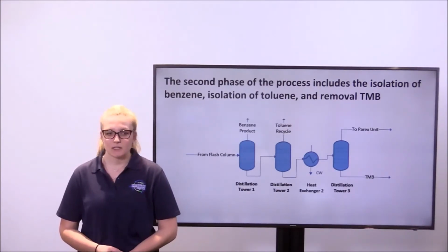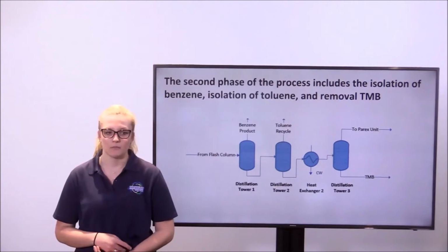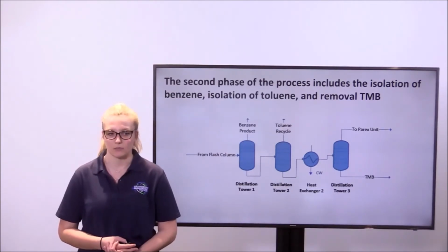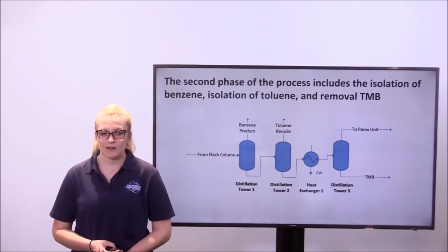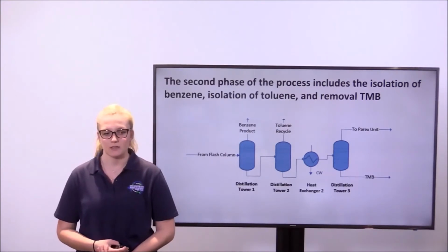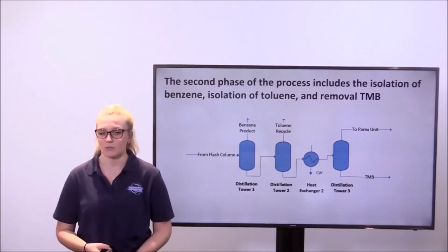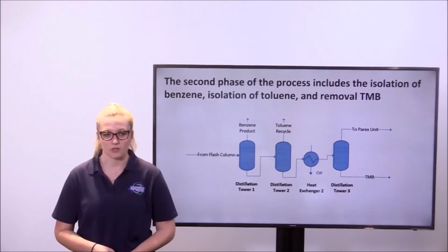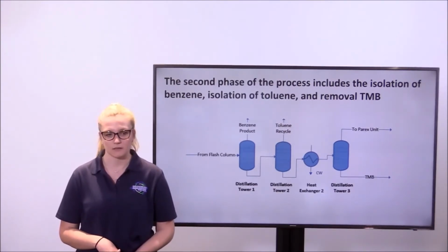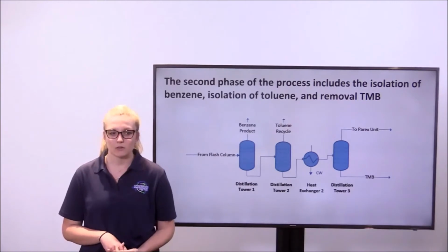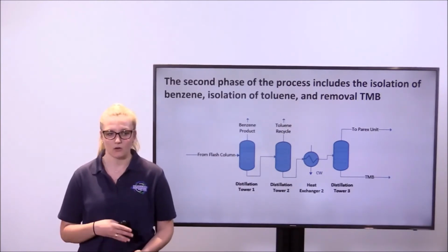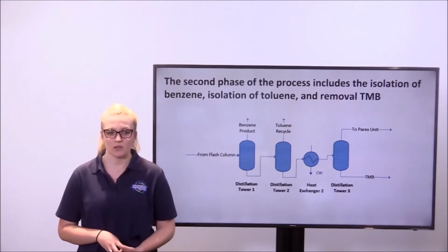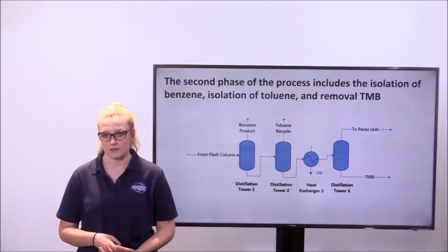The second phase of our process filters out impurities from the benzene and p-xylene products. So the first distillation tower used was designed to remove benzene, as this is a valuable product that can be sold once we hit that 99.9% purification target that we needed to sell the product. The toluene impurities filtered out in Tower 2 then are recycled back into the process so they can react further and produce more xylenes to be sold.